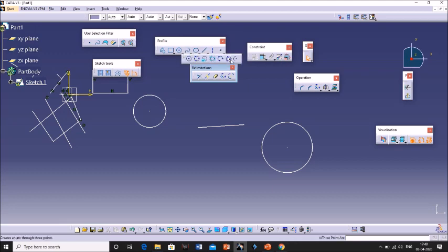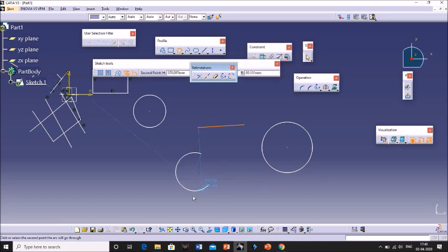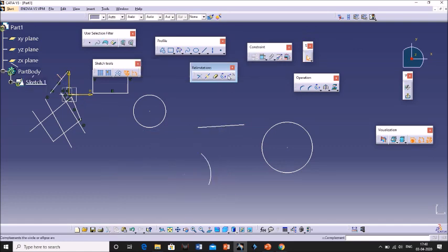So go for circle, draw an arc. So draw an arc and using close arc, select this arc. So complete circle is drawn by using the close arc. Okay. Now I am using the Control Z. So this is the half of the part of circle. Now I need to get only this remaining part of the arc.